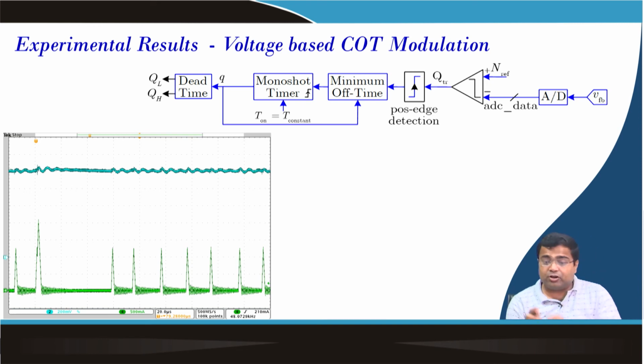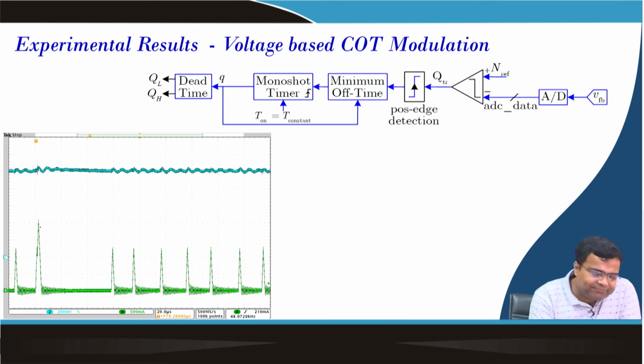Another thing, because of this time quantization, it may so happen when the on time is low, or basically input voltage is low, even if you apply an on time and your voltage is supposed to rise, there will be always some spike in the output voltage, or the output voltage may have gone down significantly, and one on time may not be enough to immediately take it up.